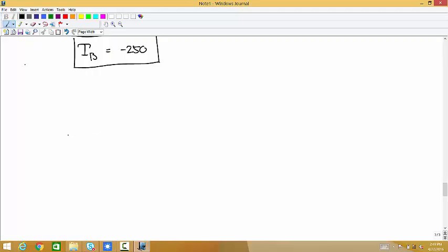If you had a beam that was cantilevered at the end, and then also supported by a roller at the other end, and you're applying some force here and some torque here, that's statically indeterminate because this thing would stand up just fine according to statics without that roller there, so it's redundant.